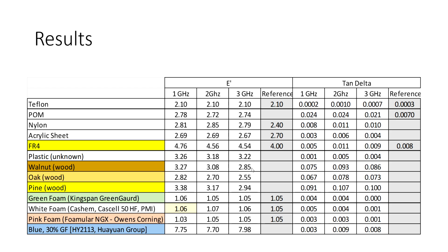The wood properties, there's nothing in the literature, and wood tends to vary based on type, density, growth rings, and so on. So unclear whether or not these wood values are accurate or not. The losses for the wood samples are quite high, which you'll note here. And it's interesting also how the wood samples do tend to change dielectric constant over frequency.